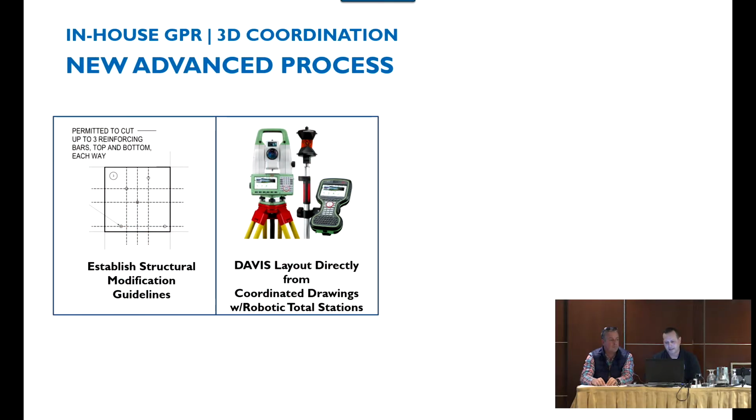We then take all the in-house technology with regards to the robotic total stations. I don't know if everybody's familiar with the total stations. Everything is based off of an XYZ point coordinate value. And they're not necessarily robots. They assist us with point layout, properly laying out points in the field with regards to how they relate to the drawings that we have in-house.